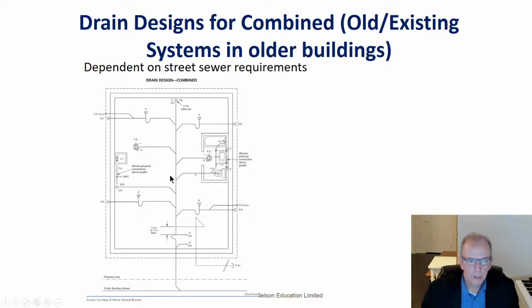Not good, because you've got all this excess water. First of all, in the city of Toronto, if you're on a street that is connected to the sanitary sewer, you've got to disconnect these and run them out on the ground. They don't want all of the water. Imagine you get a torrential downpour. All of the water that comes on the roof goes in the eaves troughs, down the downspouts, through the drain system and into the public sanitary sewer, which is carrying raw sewage in it.